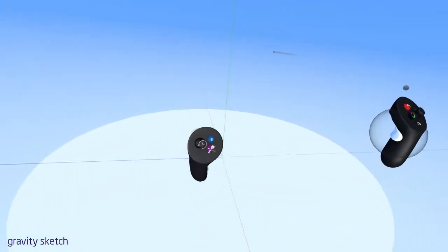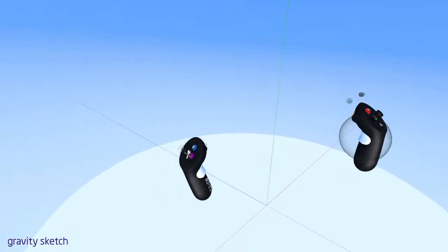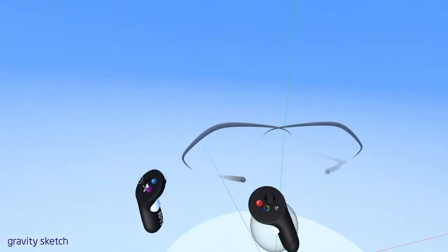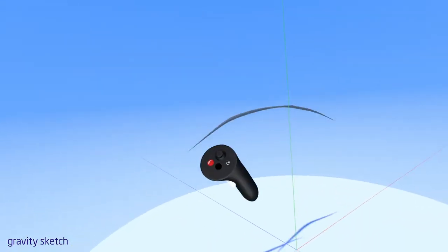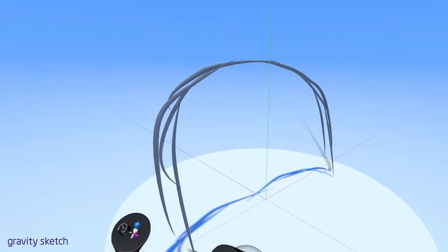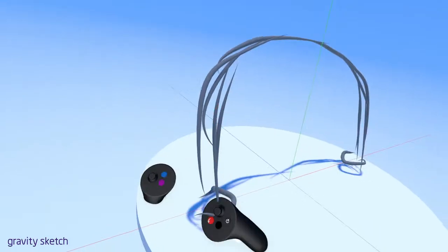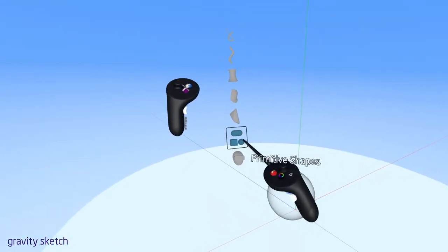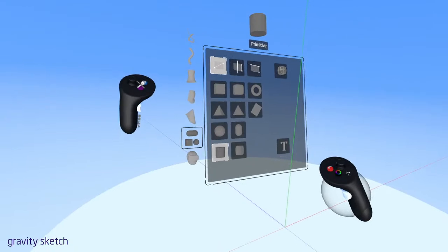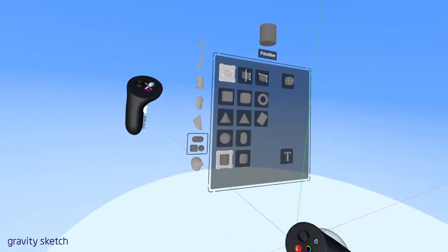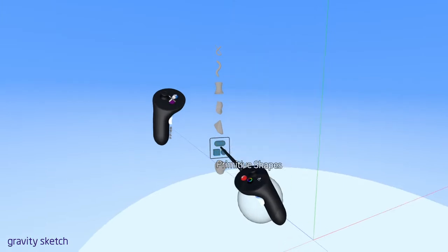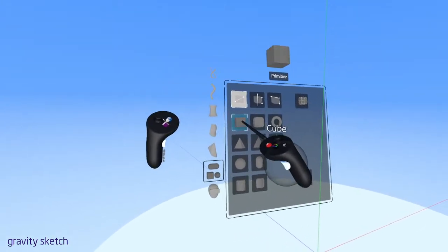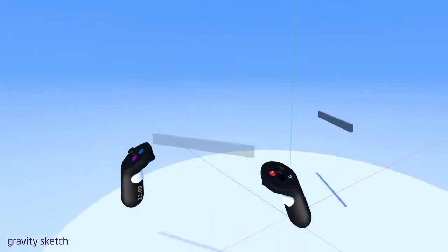So as I mentioned a couple of seconds ago, we're going to do some characters. So usually whenever it comes to characters, I start them one of two ways. I'll either start with a loose sketch like this and then start to do some surfacing on them, or I will come in here and just start from a primitive shape and use Sub-D to start placing things and getting an idea of what the volumes are going to be. So I think I'm going to do that. I'm going to click Sub-D here, I'm sorry, primitive shapes, and go to cube and drop a cube in the